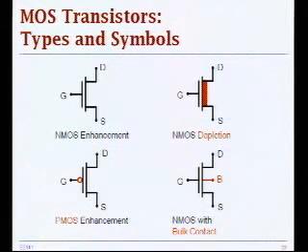This is a rather ancient device. It was popular in the 70s and 80s with NMOS logic as an active load for circuits, but it's almost non-existent in today's technologies. And then you also have the PMOS symbol that has this inversion bubble. It's complementary, works at the complementary logic levels. And then you also have this schematic representation of your transistor as a 4-terminal device.